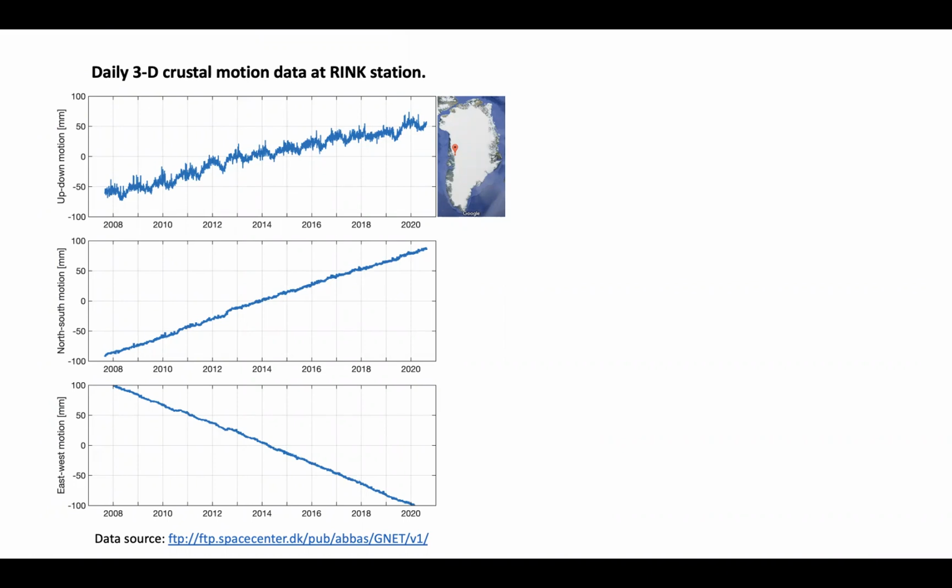For example, we had to take into account the impact of the ionosphere and atmosphere in terms of delaying the signal. And we also had to correct for the solid body tides and the ocean loading tidal effects from the signals.